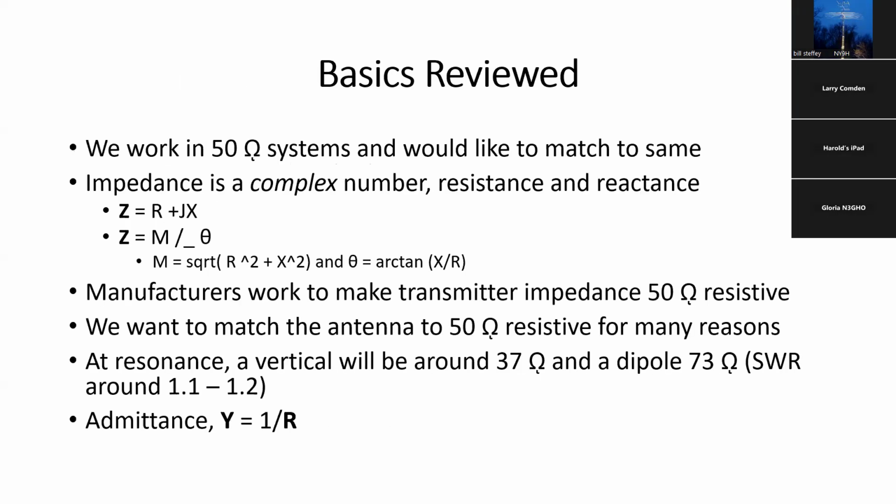Okay, so some basics from the last time that I wanted to review. We work in 50 ohm systems and would like to match to 50 ohms. We need to keep in mind that impedance is a complex number that expresses resistance and reactance. Resistance is like a resistor, and that's what does real work in our antenna situation, radiates power. Reactance creates circulating currents. And it doesn't help us with what we want to do, but it is something we need to deal with. And impedance can be expressed in 2 ways.